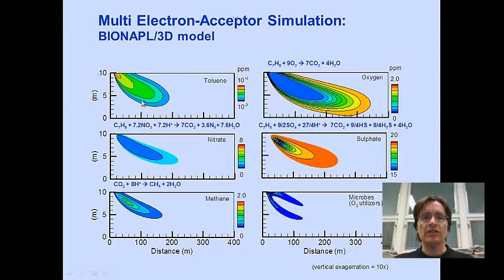So with this toluene, it's consuming oxygen. So here's an oxygen depletion plume. So we have pretty well 0 concentration here. This plume is only plotted for where the oxygen has been depleted. So this oxygen background here is a background level of about 2 milligrams per liter. And then everywhere inside this shadow plume, it's being depleted. And this is governed by our advection dispersion equation as well. You have dispersion towards the interior of this consumed plume because the concentrations are higher on the outside. And you have advection and dispersion longitudinally as well.